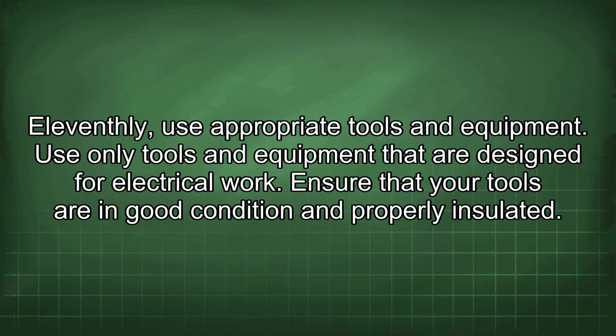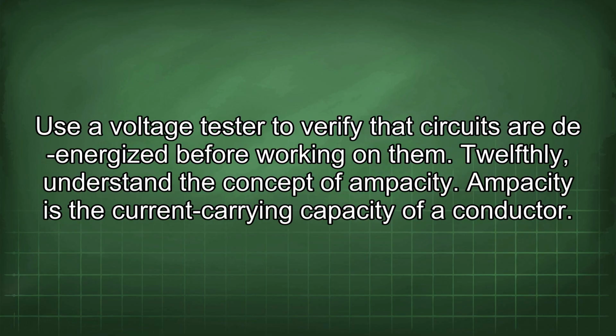11thly, use appropriate tools and equipment. Use only tools and equipment that are designed for electrical work. Ensure that your tools are in good condition and properly insulated. Use a voltage tester to verify that circuits are de-energized before working on them.